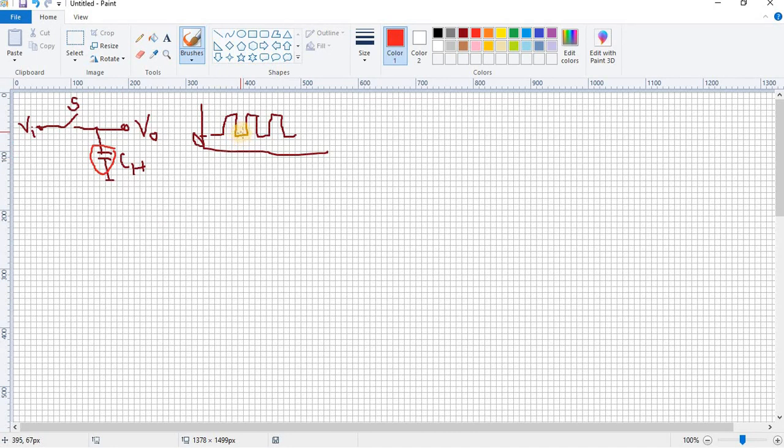So when the pulse is down, this particular switch will open, and under the condition when the switch is open, whatever charge was transferred from the input terminal to the capacitor when the switch was on is held by this capacitor. So the same charge is present when the switch is open also. So this particular circuit defines a simple sample and hold circuit, right?